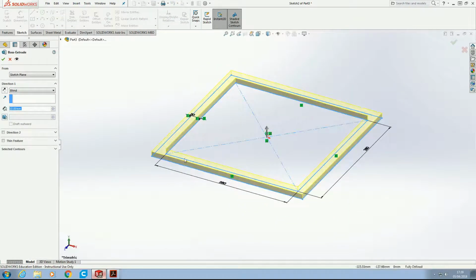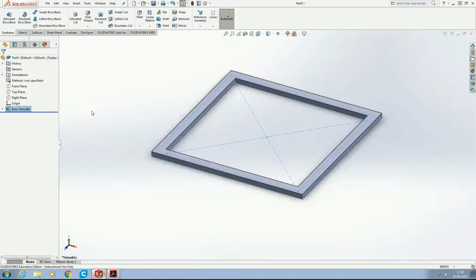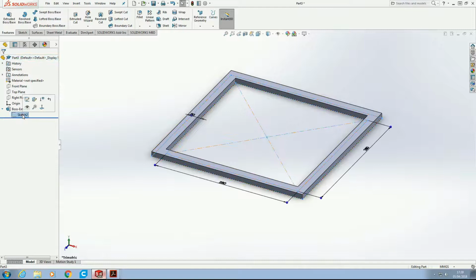Now what I want to do, obviously, is it's decided it wants to go inside and out. Okay, so it's just going to do that bit. So if we have that as 10, that's fine. And I've left that deliberately as just extruding up from the plane. Okay, so I haven't mid-planed it. All I did was come down. What we're going to do is reuse the sketch. So if you click on the sketch that's already been used, you can bring up the sketch like that.